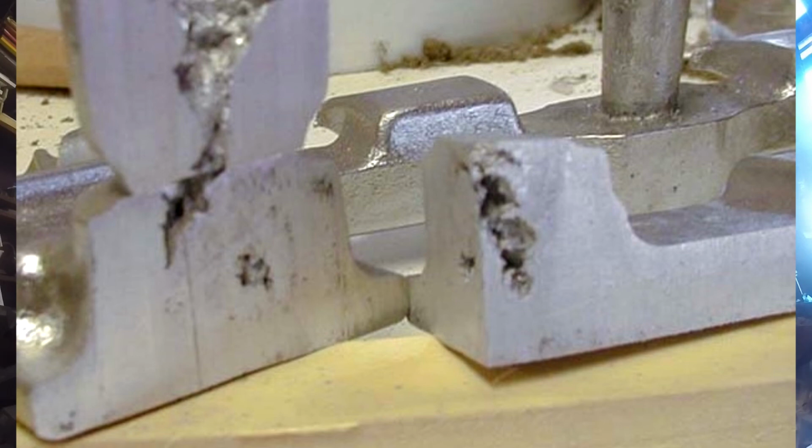And the reason I know that is because if you had that casting with solid metal on the bottom, and you only saw the piping up above inside the body of the riser, that would be a good example of why you needed a riser and how the riser should have been designed.